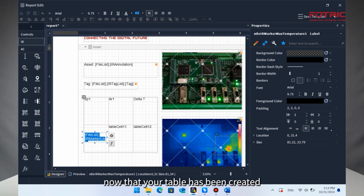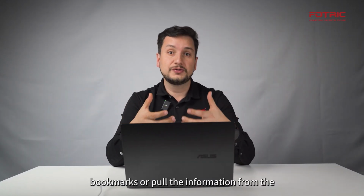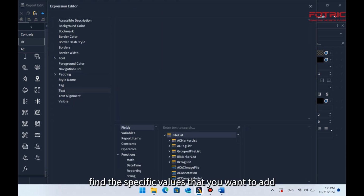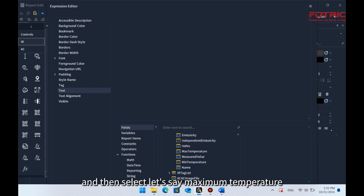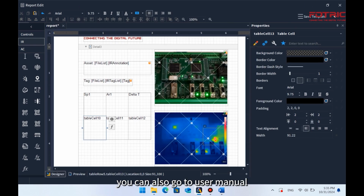Now that your table has been created, you can add the different bookmarks or pull the information from the AR image into your report template. There are different ways you can do that by simply clicking on the cell, clicking on the formula, and then go find the specific values that you want to add. Let's say you go here to IR marker list and then select, let's say, maximum temperature, double click, and then the software will create the code for you, basically. Now you can explore there, and I invite you to do it. You can also go to user manual and support, but for this video we just want to keep it short.